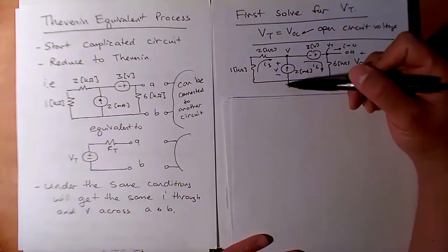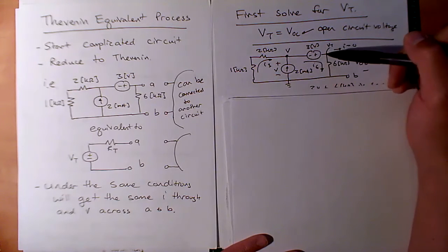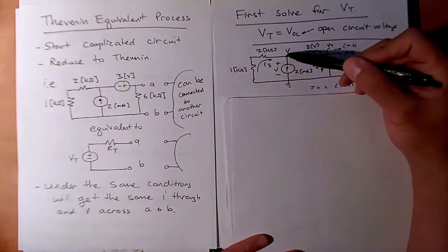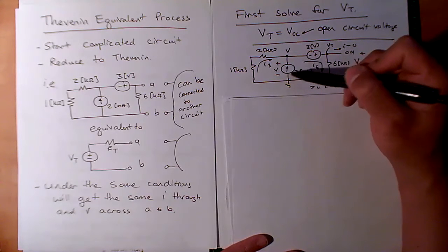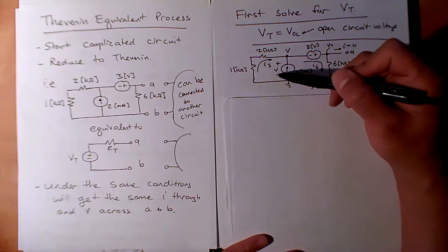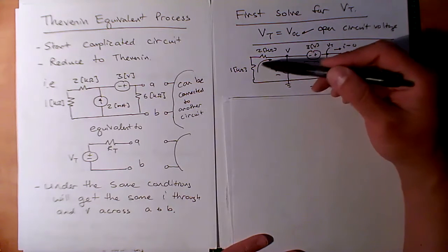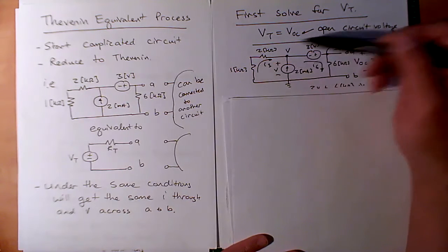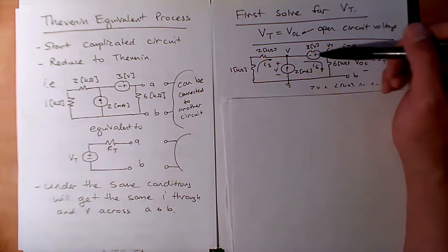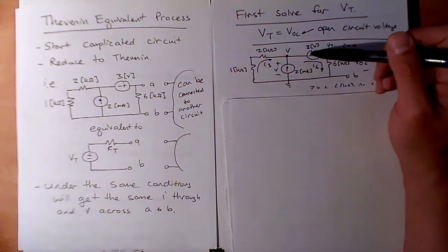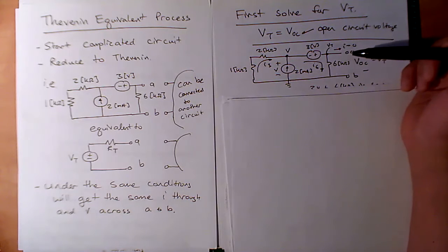So that means I'm going to set up a ground here. I can set up a node voltage here and here. I'll call this one V and I'll call this one VT. If this is V, that means by coincidence, the voltage across this current supply is also V, right? With the positive minus. See how these, they're equivalent statements. And I can also start labeling some currents. I'll call this I3 and I6. And notice, because there's no current here, these two are behaving as if they're in series. So the current here through this voltage source is actually the same current here, okay?